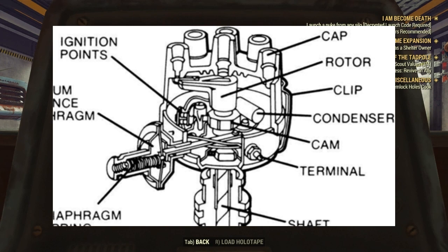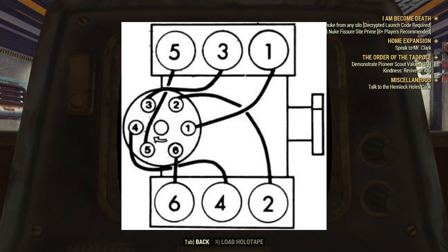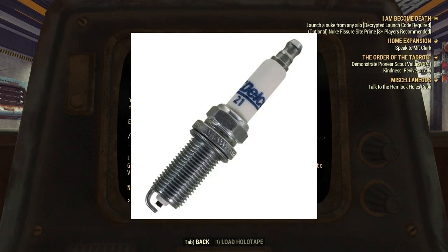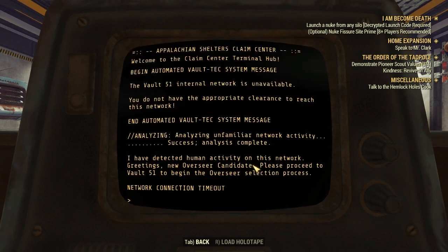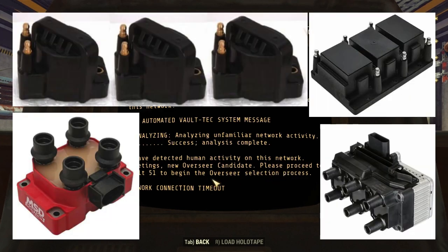From there it would go throughout all the little electronic parts in there, and then eventually go to the center, through the rotor, up to the cap, and the cap would distribute that electricity to the wires that would eventually go to the spark plugs. Unfortunately, in the early 2000s and even in the late 90s, they slowly began to phase that kind of technology out.